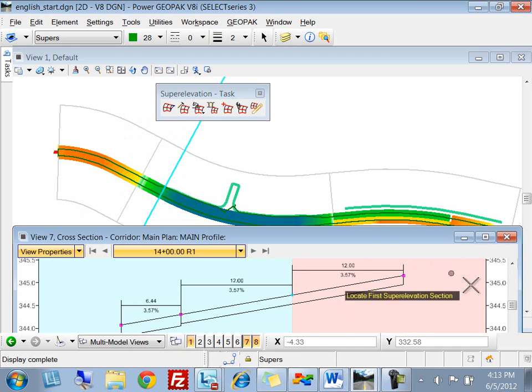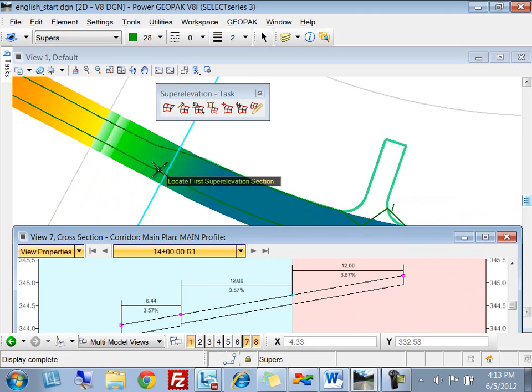And now you'll notice in this one we have the beginnings of a turn lane. And if we move in a little bit, you can see the turn lane is starting here. But you'll notice that my superelevation lane actually goes outside of the turn lane. And that's fine. It's going to build the turn lane based on either my template, or in this case, on my turn lane graphics. And so it knows to draw my supers based on my super lanes, but it will stop at the edge of my graphic. And so it basically ignores any of the superelevation lane that's outside of that. And the same thing is happening down in the area where there's only one lane. That second super lane that I drew in is being ignored as well.